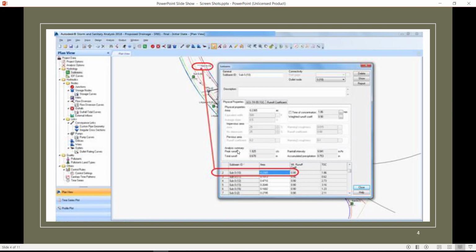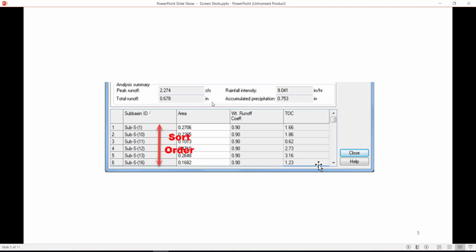In addition, clicking the column header at the top of the table allows you to sort the data in descending order, as shown in the following figure. For example, using this feature allows you to quickly find outliers in the defined element data where there may have been a data input blunder. Sorting the column allows you to see if there are any elements with unusual values or perhaps a missing value.